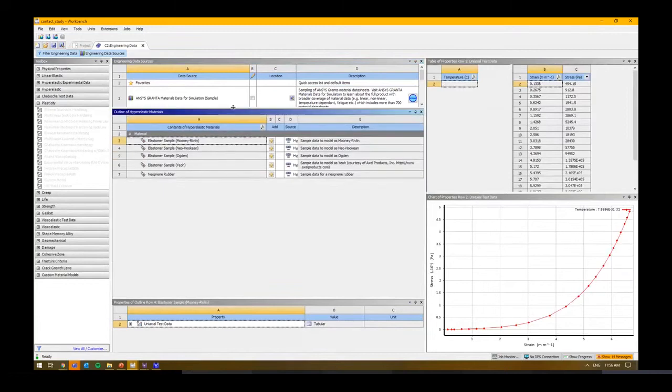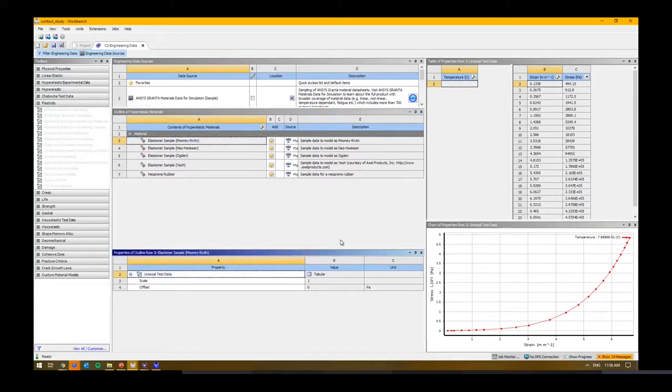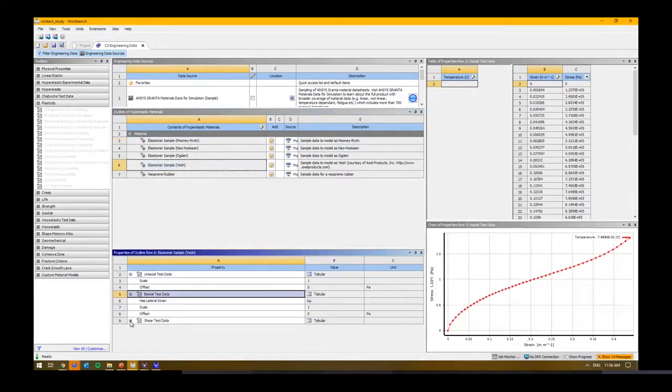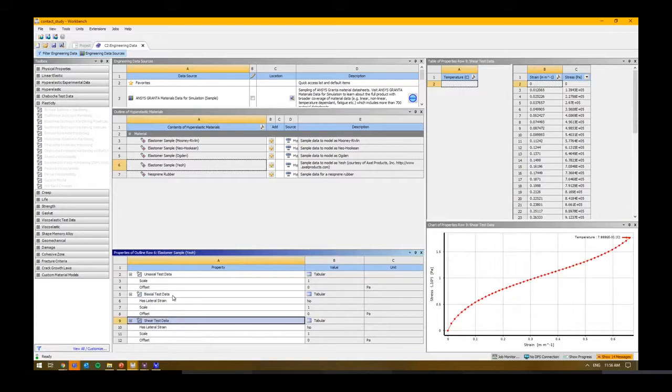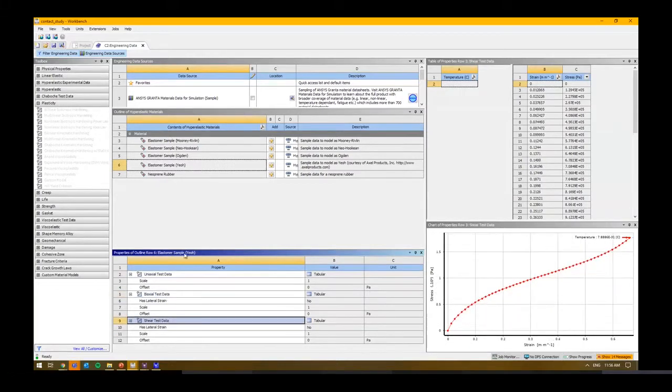So you'll notice, for these like rubbers, right? There's different models that can be used. So in this particular case, using the Mooney-Rivlin model, we've got stress and strain, and there are other things like the Yeoh, which requires more data, right? So it requires shear, biaxial, and uniaxial tensile, right? You've got all of those compared together, and that actually gives you the material properties of that component, right?